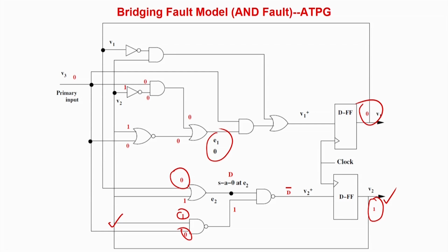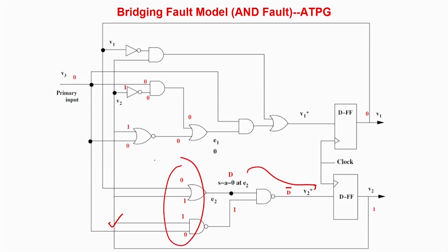So how do I do this? As all these flip flops are scan flops, I can just disconnect these two and make them 1 and 0 by the scan manner, and then I can go for this approach. So directly the flip flops are controllable, that is what I have assumed. So this is what I propagate the value over here, and this is the requirement over here.